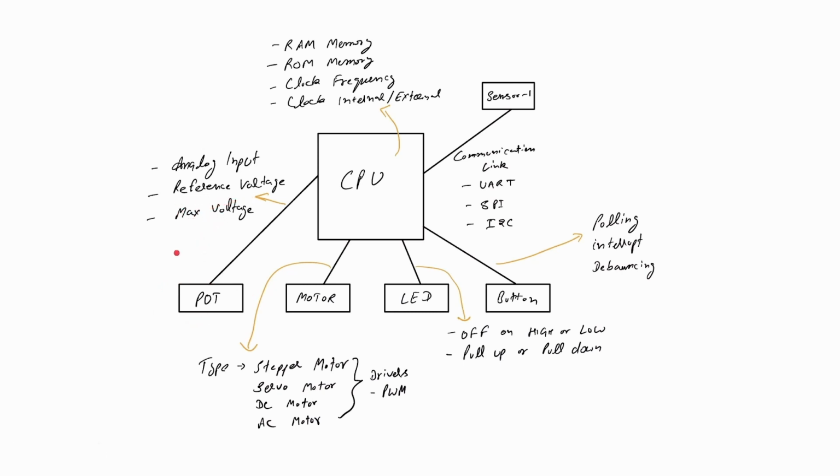to convert it. And the next step would be finding out the memory of the CPU and the flash storage of the CPU and also the clock frequency, and make sure the clock is properly initialized. These steps nowadays are normally done by the vendor. You have example codes to do that, and some vendors such as ST and Microchip provide some code configuration tool. You can do all these settings using a graphical interface, which is very easy nowadays.